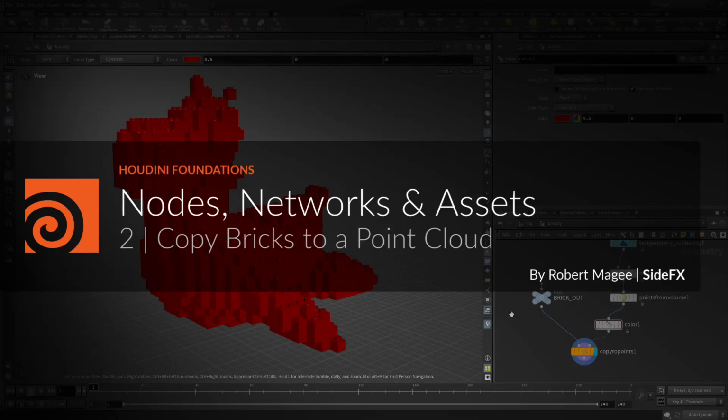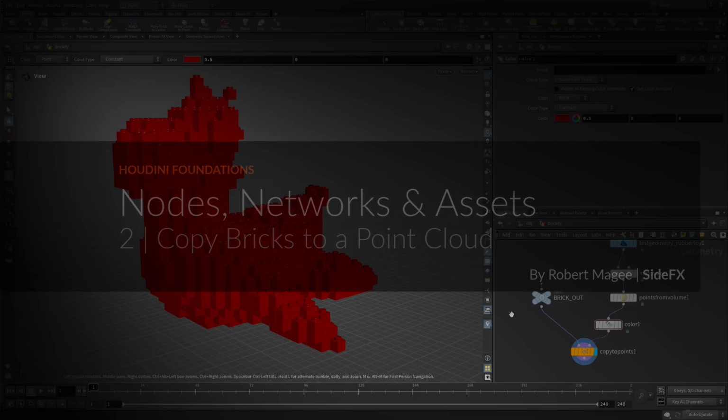Welcome to part 2, where we're going to copy bricks to a point cloud. You're now going to create a cloud of points that match the shape of a particular piece of geometry. You are then going to instance the bricks to the 3D grid to create a brickified version. The instancing is generated by packing the brick geometry and then instancing them to the points.